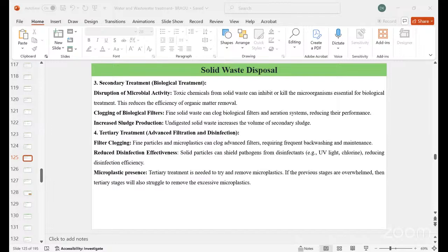So coming to the rotary kiln incineration process, which uses a rotating cylindrical drum where waste is fed and incinerated under controlled temperatures between 850 to 1200 degrees centigrade. The rotary kiln incinerator breaks down and decomposes material into simple compounds via complete combustion, converting the waste into an ash residue and thereby significantly reducing the waste volume.